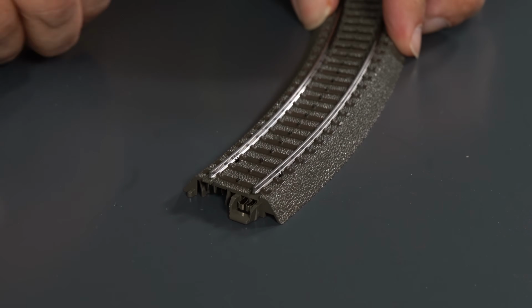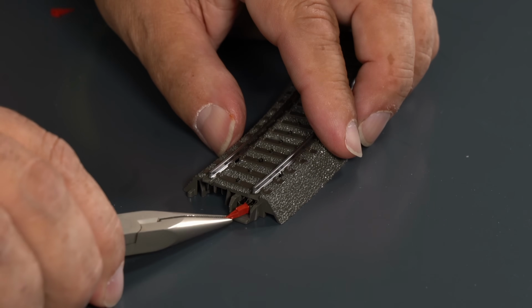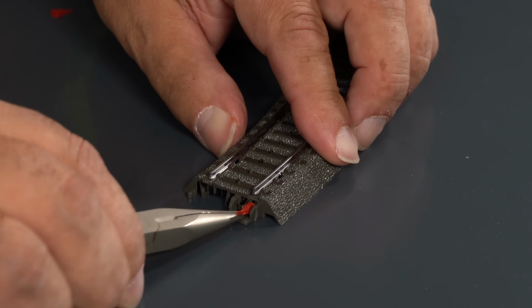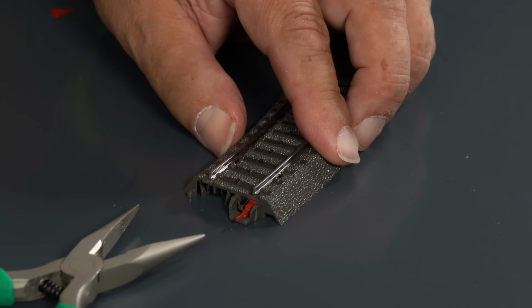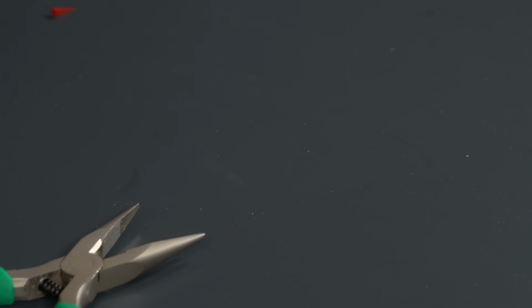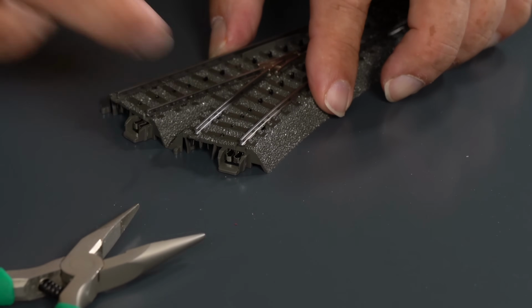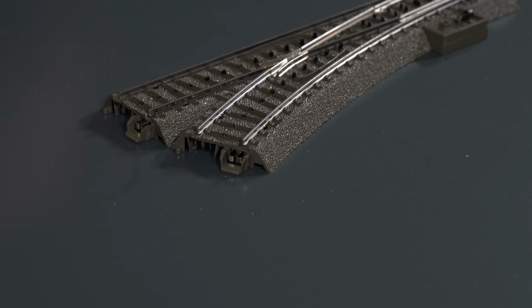And now in the second to last step, I of course need to equip the corresponding side here with the insulating cap. For this, I usually use a small pair of pliers, gripping the tip of the insulating cap a bit more firmly and then carefully inserting it on one side. After that, I press the whole thing in accordingly. This way the insulating tab is perfectly installed right here, and of course I have to do the same thing with the turnout as well. That means this spot also needs to be fitted with this insulating tab, just like before.